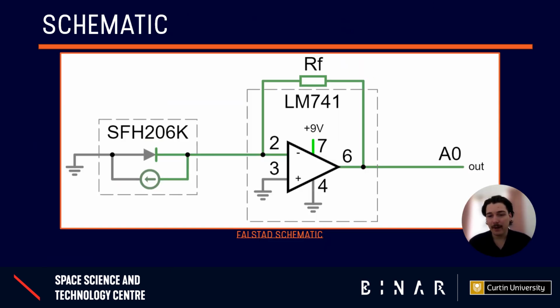This is the schematic diagram of our circuit. As you can see, the parts have been represented with their corresponding symbols and labeled with boxes. When you see an integrated circuit or a chip like the LM741 op-amp, you should also label all the pins so that when you build the circuit, it's easy to match the numbers.